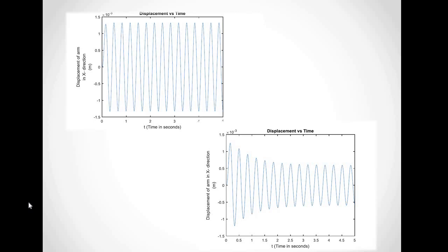A similar result of displacement of hand, the second diagram, with the vibration absorber system in horizontal direction, and the results were carried out in a time and frequency domain for a period of 10 seconds at the 3 Hz frequency. You see in the second diagram, the reduction of the vibration happened.